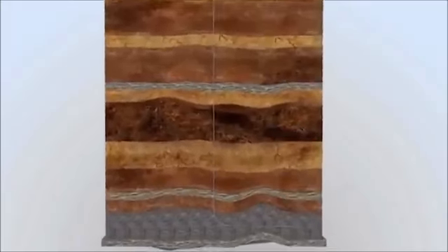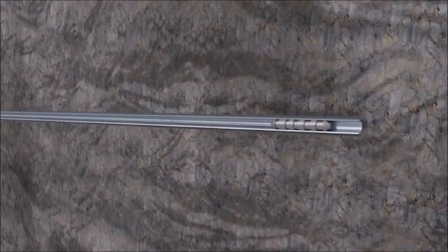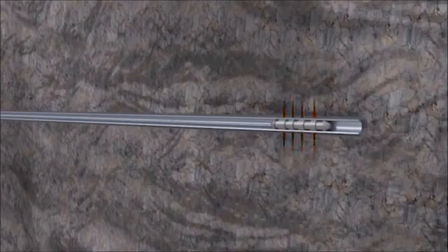The first step in completing a well is the creation of a connection between the final casing and the reservoir rock. This consists of lowering a specialized tool called a perforating gun, which is equipped with shaped explosive charges, down to the rock layer containing oil or natural gas. This perforating gun is then fired, which creates holes through the casing, cement, and into the target rock. These perforating holes connect the reservoir and the wellbore. Since these perforations are only a few inches long and are performed more than a mile underground, the entire process is imperceptible on the surface.